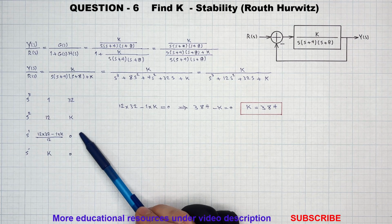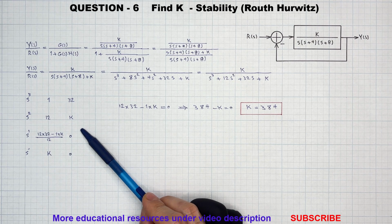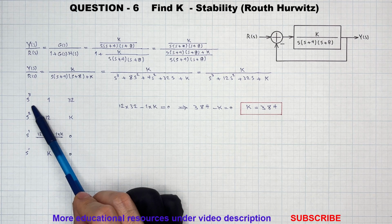Then we construct the Routh table. The Routh table is a structured array formed using the coefficients of the characteristic polynomial. The first row corresponds to the coefficients of s to the power of 3 and s to the power of 1, which are 1 and 32.